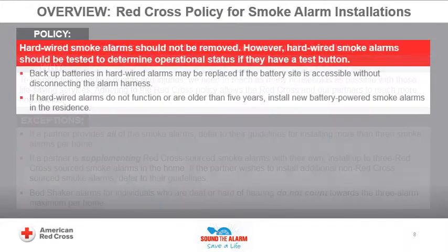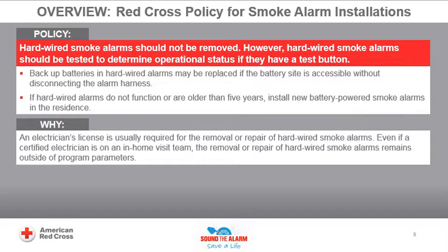Policy: hardwired smoke alarms should not be removed. However, hardwired smoke alarms should be tested to determine operational status if they have a test button. Backup batteries in hardwired alarms may be replaced if the battery site is accessible without disconnecting the alarm harness. If hardwired alarms do not function or are older than 5 years, install new battery-powered smoke alarms in the residence.